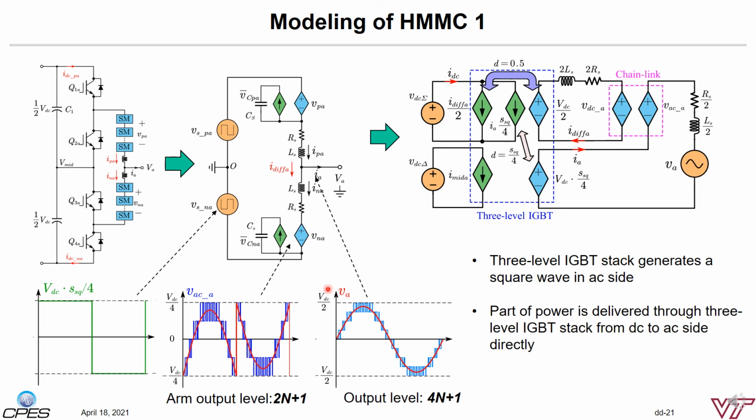In addition, as just mentioned, the AC output voltage is created by stacking the square wave with MMC arm total output voltage. Compared with MMC, although HMMC arm creates half number of the voltage levels, the total number of the voltage level on the AC side is the same. Therefore, HMMC will deliver the same AC output quality as MMC, without need to change the submodule switching frequency.